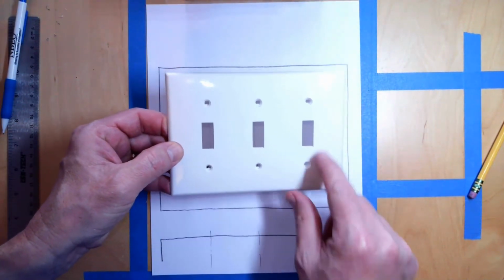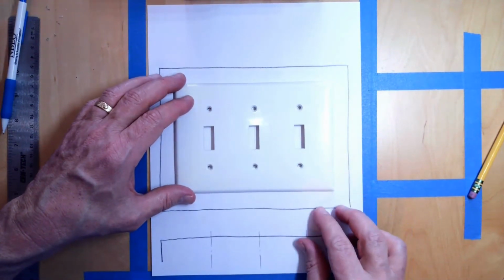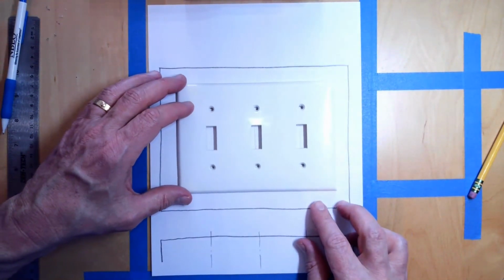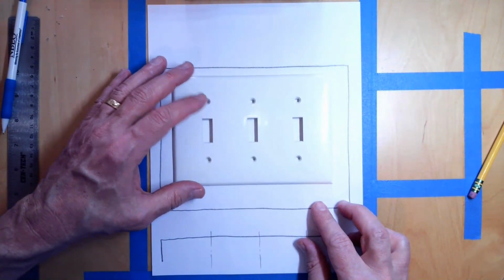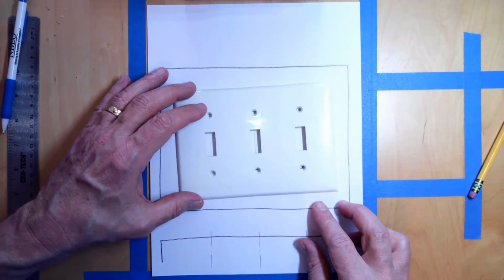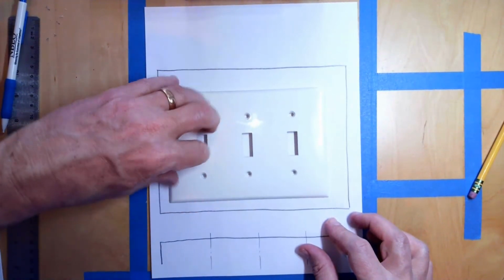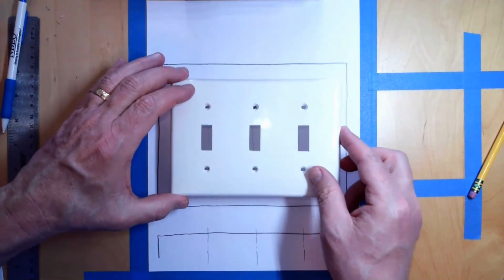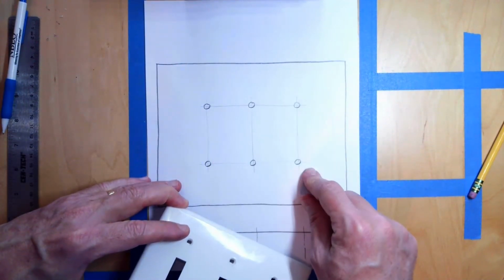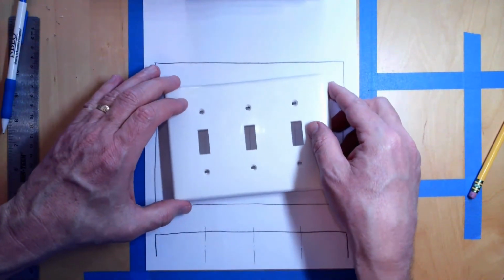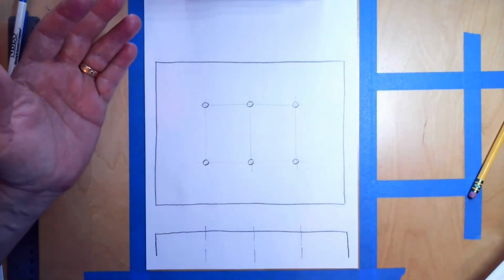What I can be looser on is the holes relative to the sides here. As long as I maintain the orientation of the 6 holes relative to each other, it's not a big deal in my design whether all 6 holes are a little bit closer to the right or a little bit closer to the top or even a little bit at an angle. That's not important. In order for the cover plate to still function as a cover plate, the holes must line up relative to each other, but it's not so critical their position relative to the sides.